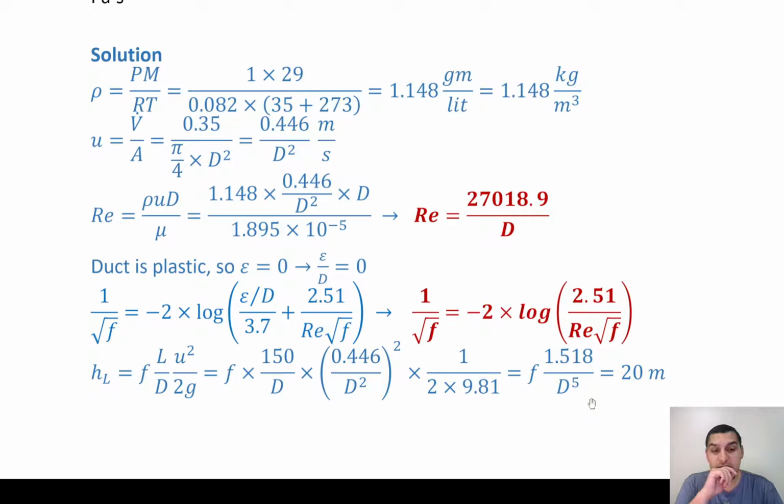But in case of turbulent flow, it's going to be d power 5, which means that if we have the same case, the same diameter and the same losses, and the diameter is reduced to half, it's not just only increasing one number in the power. This number in the power means that the loss in laminar flow is going to turn from 1 to 16, in turbulent flow it's going to be from 1 to 32. So it's double the loss in case of laminar flow, and this is a lot. Having this pressure drop increased from 16 to 32 is a lot, and it can mean a lot of money that we need to pay for pumping